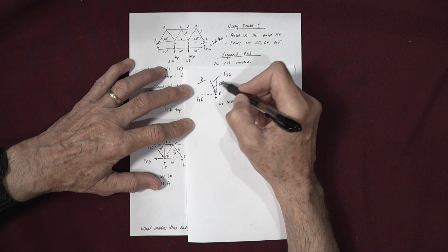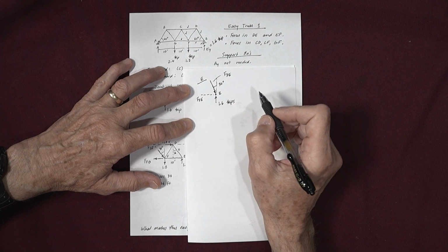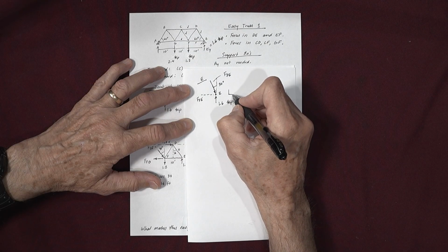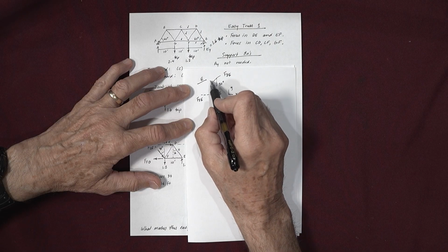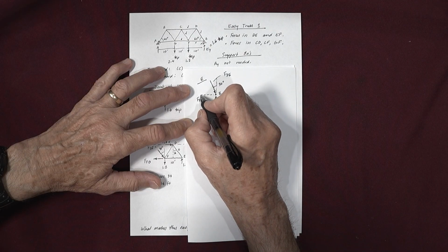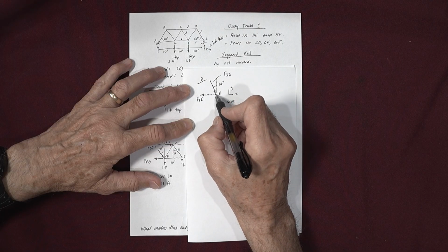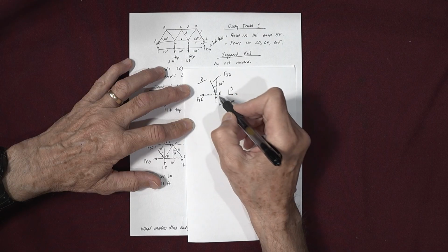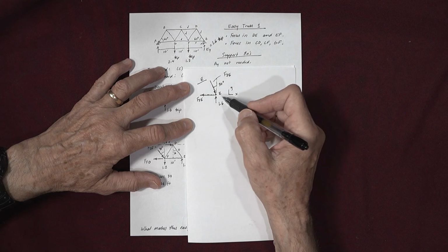Well, once you draw FDE properly to keep this joint in Y equilibrium, now we're going to draw FFE. And so E is going to have to be in equilibrium in the X direction. If I put some coordinate systems on here, this is X and this is Y. The horizontal component of FDE is pushing to the right. There is no horizontal component of the reaction. So FFE is actually going to have to pull to the left so that its horizontal component is equal to that of FDE. And that basically places FFE in tension because it's pulling on E. Can you see that?